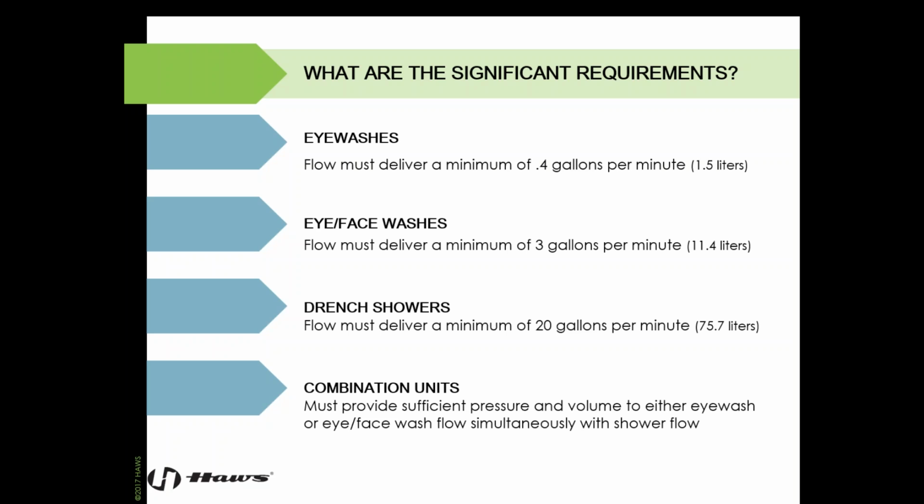A question that we get often is how much of the face needs to be covered. That is not identified in the standard, so when you are deciding on an eye face wash, definitely look into the flow patterns and seeing how much of the face it covers. The more, the better.